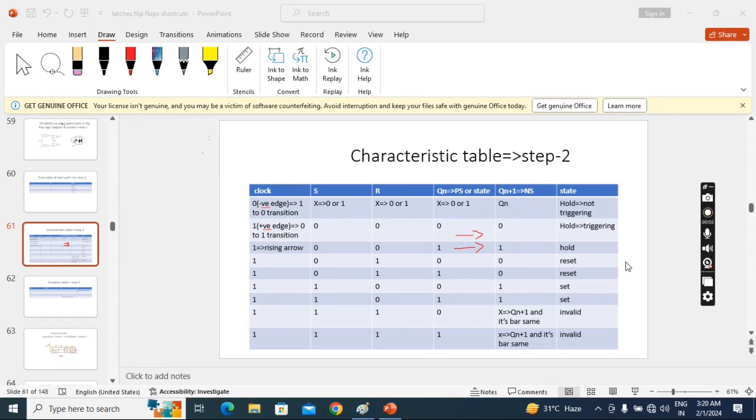In this lecture, we'll see the use of SR flip-flop. Ultimately, this flip-flop is a 1-bit storage element. We have to store bit 1 and bit 0. In the set condition we are able to store 1, and in reset we are able to store 0. So it is storing 0 and 1, acting like a 1-bit memory element. Other flip-flops also give set and reset possibilities, not only SR.